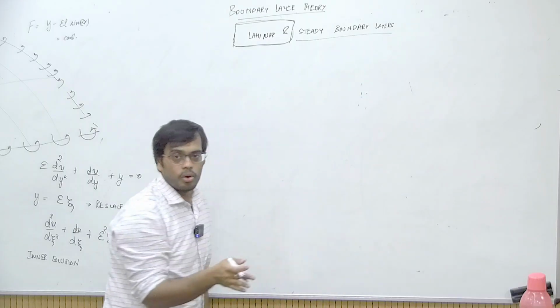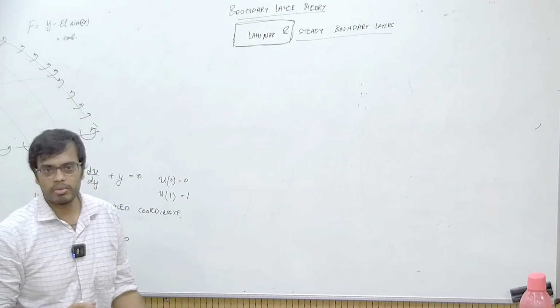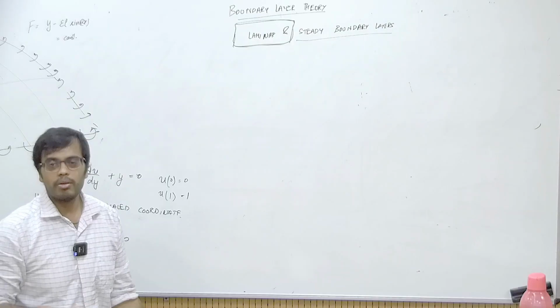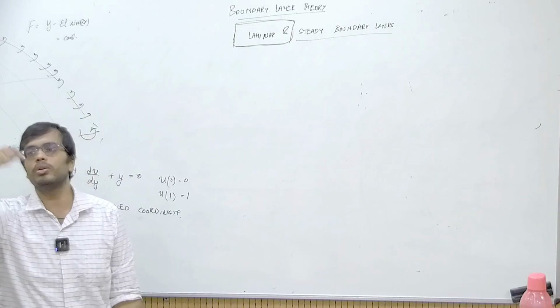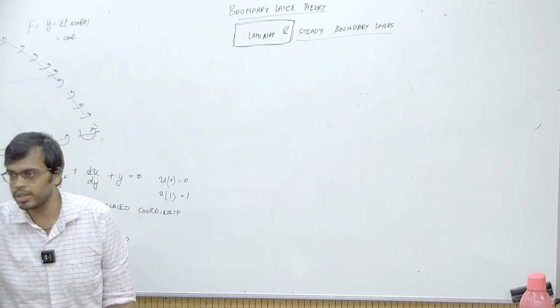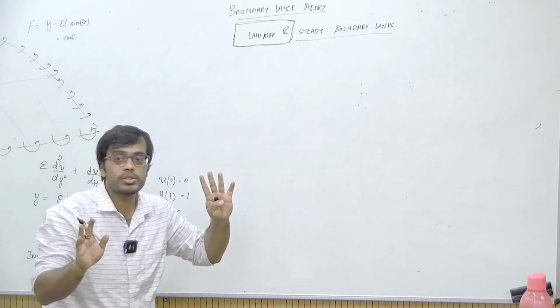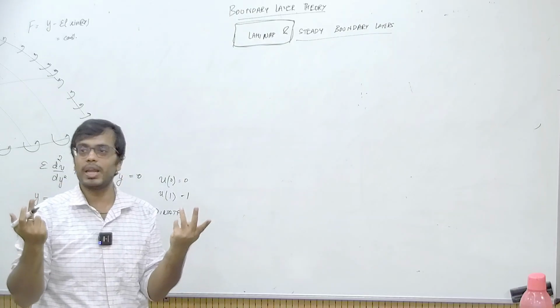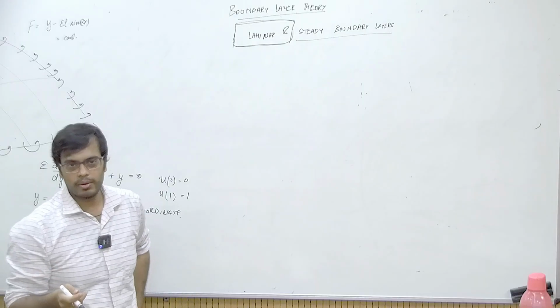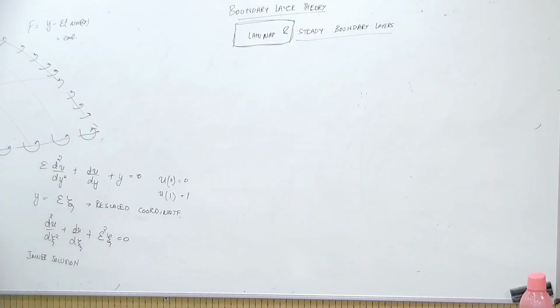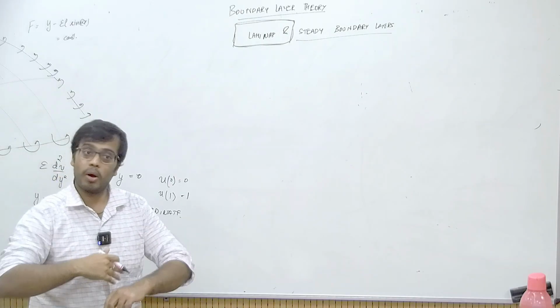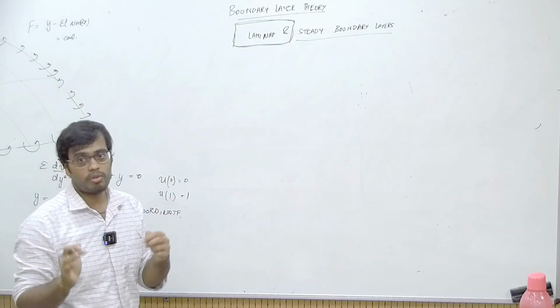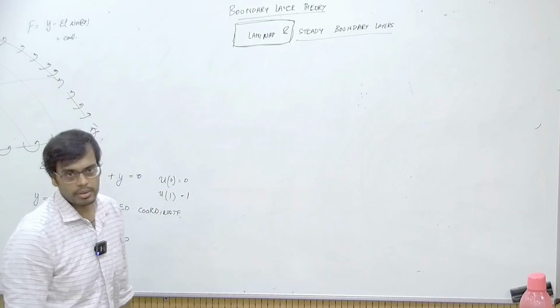Steady, we know, we ignore the unsteady term in the governing equation. Uniformity, we know, let's say if it's uniform in x, we ignore del by del x terms in the governing equation. But we don't know what to do when we solve assuming a laminar solution. So you can just qualitatively remember this, and after we have done instability, it will become clear to you why all the solutions that we have found are laminar.